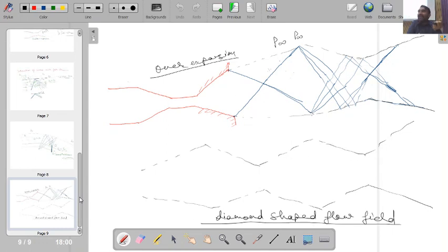oblique shock waves, there we had the assumption of two-dimensional flow, and that two-dimensional flow also, by using some geometric transformations, by using normal and tangential components across the shock wave, we have finally employed the normal shock relations only, okay, by using some geometric transformation. So we have tried to make that flow also analogous or simpler to a one dimensional flow situation. Then the third important aspect we have studied in this particular section, flow through nozzles and diffusers, and in this section also we have taken the important assumption of quasi one dimensional flows.